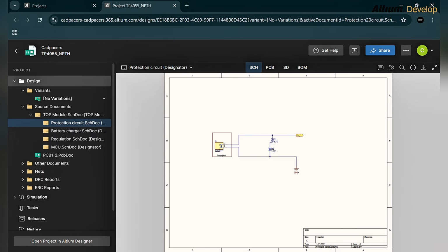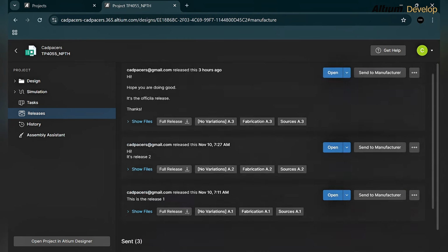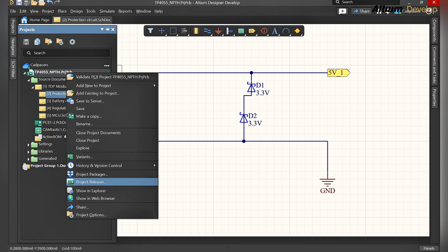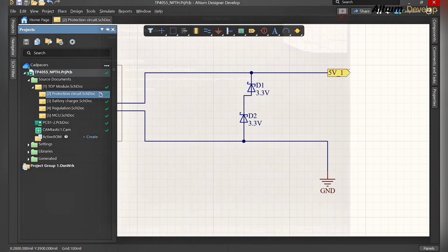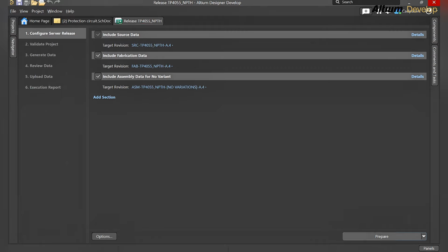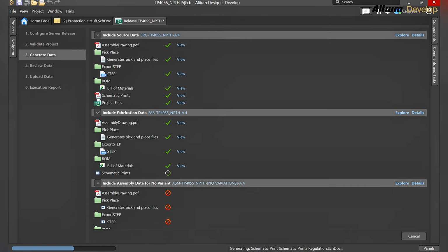Visually we can see in the schematics file that it's removed, but how can someone see in the BOM that the fuse is not used now? We don't need the fuse now, so how can he do it? We will see it by releasing the project and comparing the BOM of the new release with the previously released file. So let it be done.